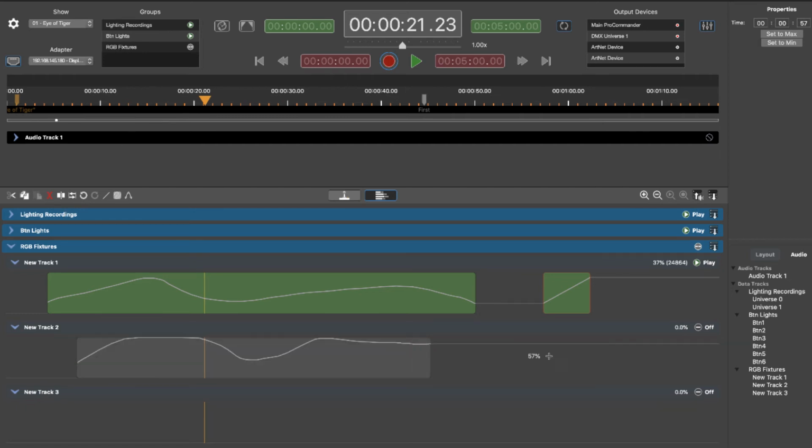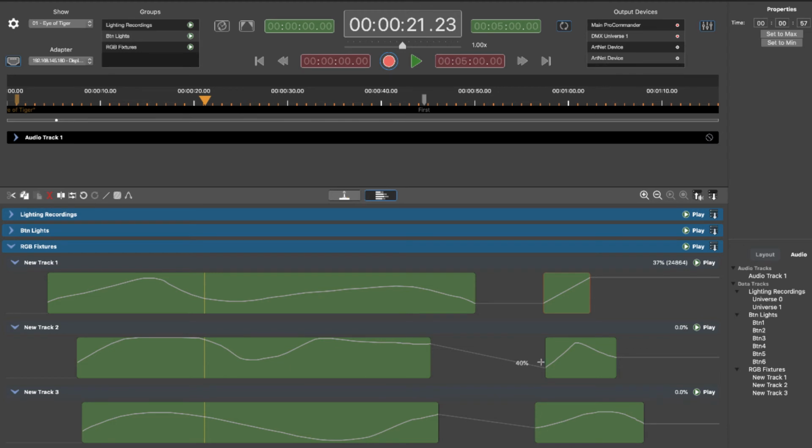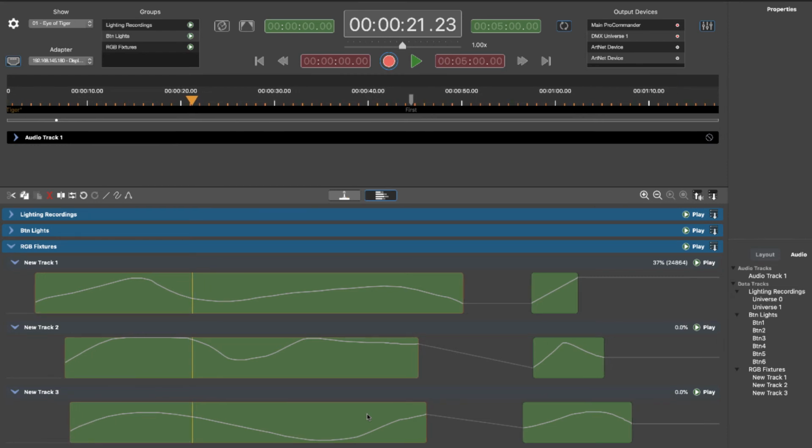Under here, if I create similar data to show me the synchronization between R, G, and B, notice I've got these different levels here, and I'm going to change that whole group into play. This curve here, where there actually is no data, represents almost like a ramp or a fade time between one cue and another. However, note that everything in Showforge is based off linear interpolation, and it is not going to actually crossfade like you'd have a Lightboard output playback setup. This is actually better for motion control and can give you more of a smooth or linear ramp.